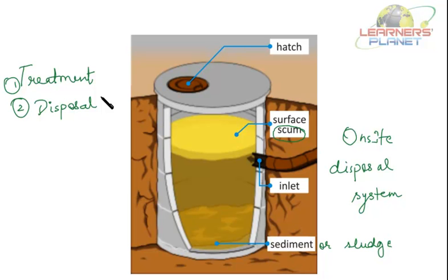You will be amazed to know that septic tanks were originally developed in the 18th century and have changed little over the past century. A septic tank is a large watertight container of approximately 1000 gallons, which is generally buried slightly below the surface of the ground adjacent to the building it is serving. In the tank, solids settle to the bottom and fats and greases collect in a layer on the liquid surface, which is called surface scum. The outlet of the tank is constructed so that the liquid is discharged from the layer between the solids and the scum, and the solids and scum are then dumped from the tank approximately every 3 years. That is why it is said to be a low-cost on-site disposal system.